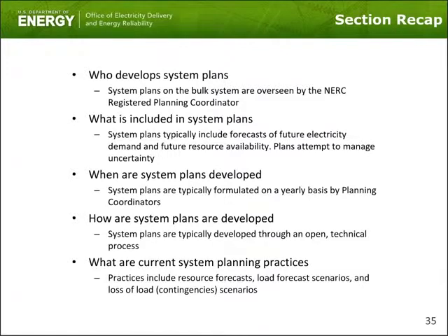System planners also need to accommodate how system demand or load will grow or decline in the future based on a number of econometric attributes. The planner will take into account how policy mandates require the system to be designed and/or operated. This can include a focus on system performance, i.e. setting performance for loss of load expectation calculations, which are typically 1 day of load loss over a 10-year period, to how the system is designed and operating, including a focus on installed and planning reserve margins and the percentage of renewable generation sources on the grid.